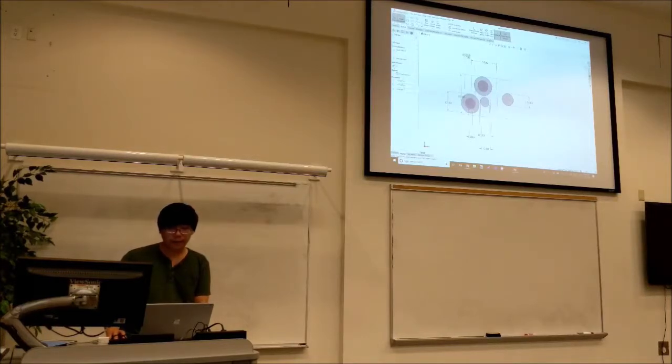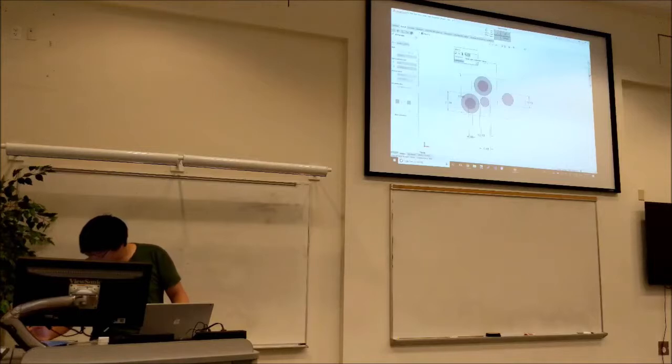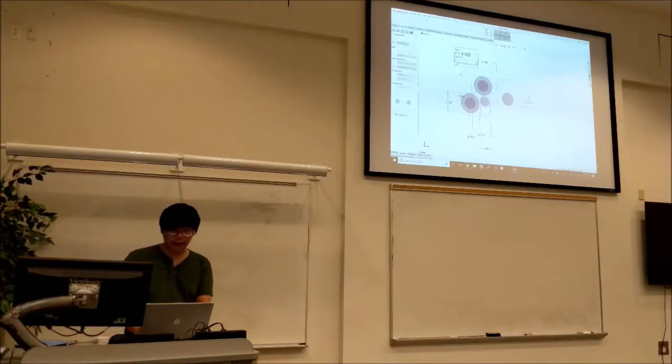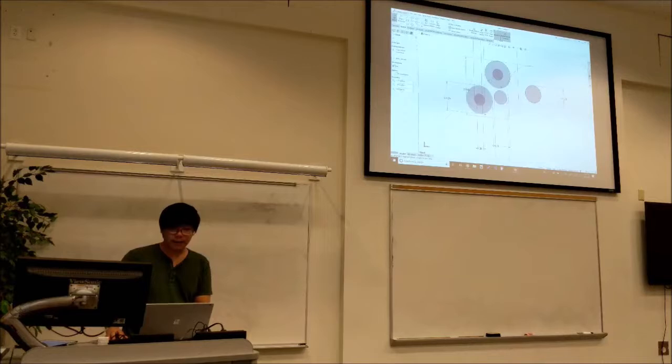And then here, the part that goes into the plate, the part that protrudes off the 775 Pro, I believe it's, let me double check. It's 17.8 millimeters. And then the motor is not part of the actual plate, of course, so we can make that construction geometry. This is not construction geometry because it's actually going to be a hole in the plate.